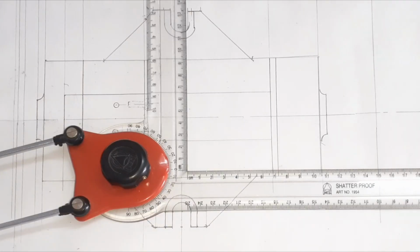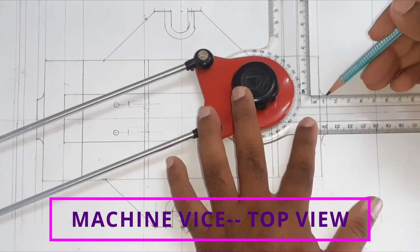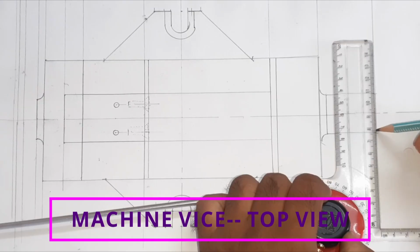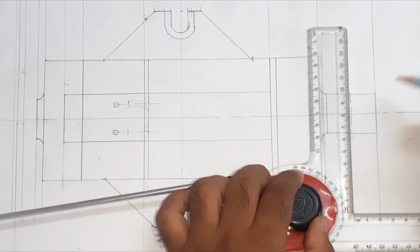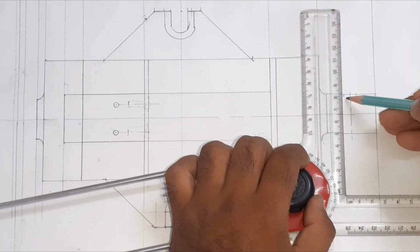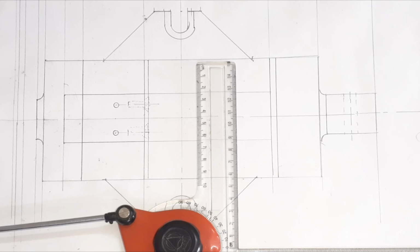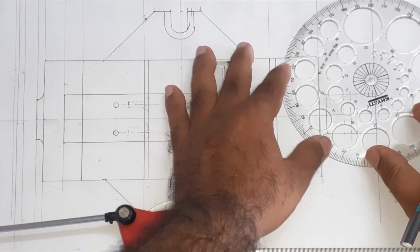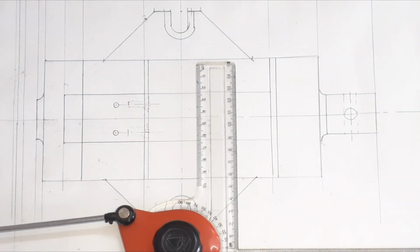Here we have already drawn the axis line, so it will be easy for us. Here you can see we have drawn this one. Next is the axis line, which we will get from the front view only. Next are the dotted lines. We will mark this dotted line similarly from the front view like this. Next step is we have to draw a circle here of 10. Here you can see the circle of 10, right. The next step for us is to draw the rod.